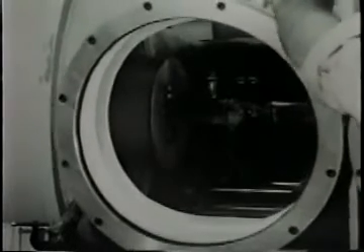Right above the washer, we've placed the slit which defines the beam of sodium light. We control the test chamber pressure with vacuum pumps downstream, and the flow is under free molecular conditions. We'll use a horizontal line to show the length of the mean free path of molecules approaching the washer. For this flow, it's rather long. Here's the Knudsen number. The characteristic dimension, d, in this case is the diameter of the washer.